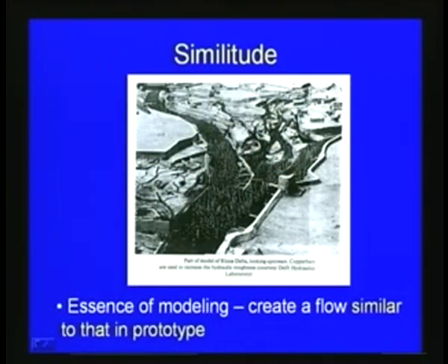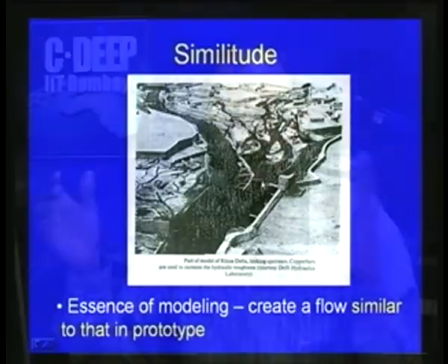While doing this modeling exercise, we have to understand the important parameters and analyze them. When we develop the model with respect to the real physical problem, or the prototype, we have to see which are the dominating parameters, and those parameters we have to consider in the scaled model which we develop in the laboratory. Here in this slide you can see a model of an estuary problem, wherever a river is joining the sea. Here the length scale, width scale or depth scale, we may not be able to follow the same way.